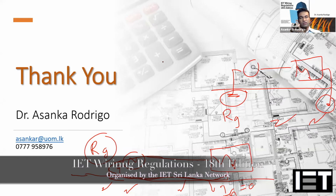That's why the utilities are now asking that if you have that type of underground cable, it is better to put an RCD there. In any case, if there is an earth fault situation, it will be taken care of by that RCD. In the traditional system, when you have insulated cable, a single insulation failure, nothing will happen, because you have mechanical protection, a double insulated cable, and a conduit as well. But if you have two insulation failures, like the live wire failing, then that will be detected as an overcurrent